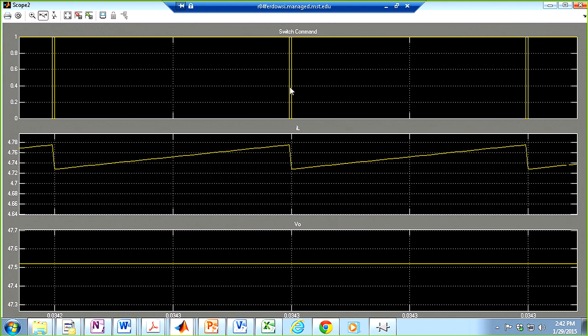Physically, they are going to be larger, so your converter is going to be bigger and heavier. The other issue is you have to pay more. And the third issue is your system gets sluggish, especially for the capacitors. It took a long time for the system to settle. So there are trade-offs. On one side, your large capacitor guarantees a good DC output voltage, which is great, very small ripple, but the downsides are sluggishness, large weight and volume, and higher costs. Inductor is almost the same thing. Okay.